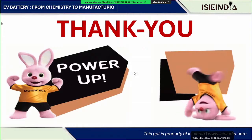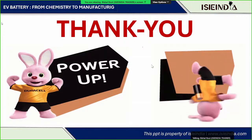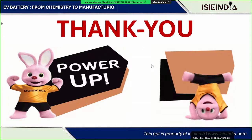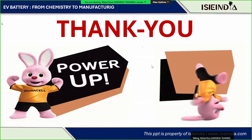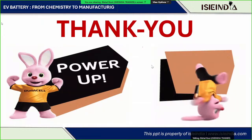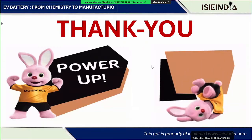See, if we go to any certifying agency and ask them to do the test, they will generally perform 13 tests. One is the vibration test. Another is the mechanical shock test. Then the drop and impact test. They will perform the thermal shock and thermal cycling test, which evaluates how the battery will behave under rapid temperature change conditions.